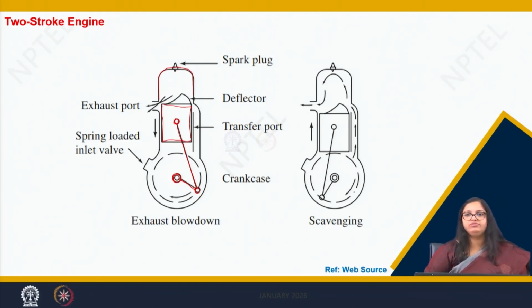Instead, we have 2 ports here. One is a spring-loaded inlet valve. It is also like a port, but it is spring-loaded. There is a spring which is attached here, which helps in opening of this inlet valve. So that is why we call it a valve. And then there is a port here. There is just an opening which helps in taking the burnt out gases out of the combustion chamber.